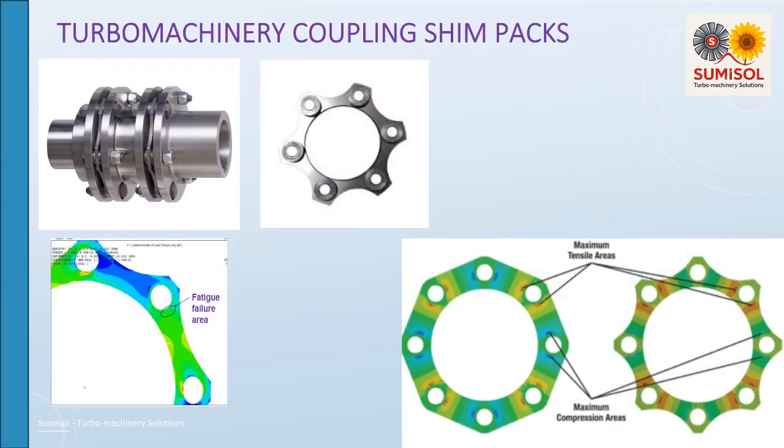Disc pack couplings membrane axial deflection stresses. Maximum stress occurs in areas where the discs are wrapped around the curved element washer. Tensile stress on top surface. Compressive stress on bottom surface. Midspan and edge stress are relatively unaffected by axial misalignment.